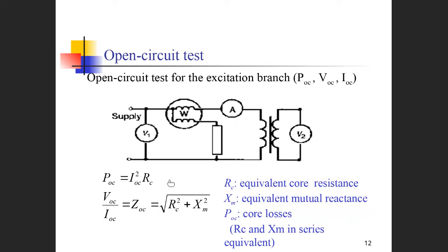As such, the input power will reflect the core losses of the transformer at rating voltage. The input voltage over the output voltage will represent the general transformer ratio of this transformer.